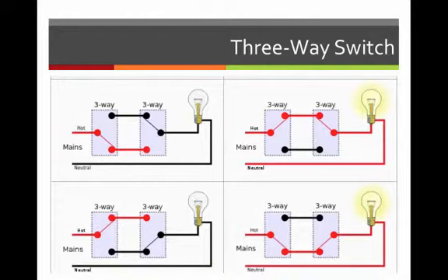Okay. This diagram is really great in that it shows us a couple of things. I'm going to explain it, start in the upper left and work my way clockwise. So over here you have your feed wire, that wire that would be coming from your electrical box in your home, and you have a hot wire and a neutral wire. Usually this hot wire is black, neutral wire is white, and then usually you have a ground in there.